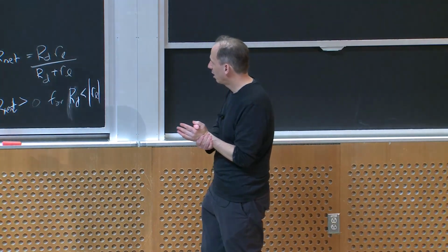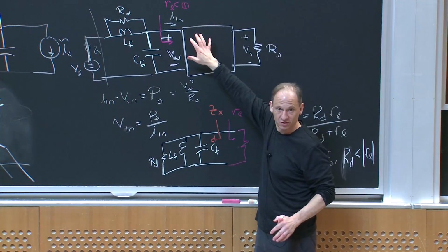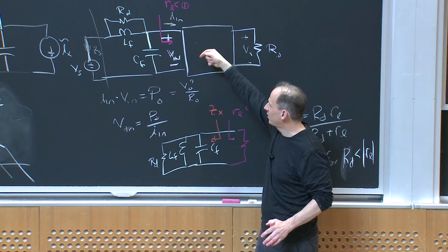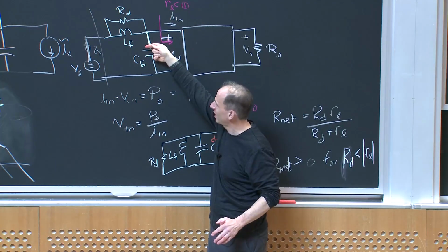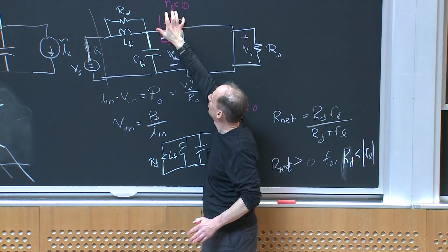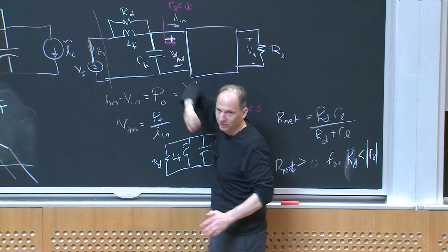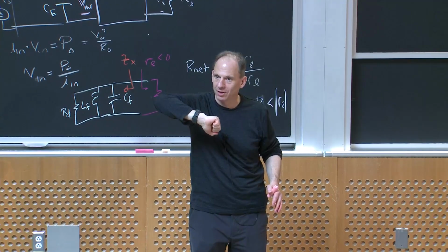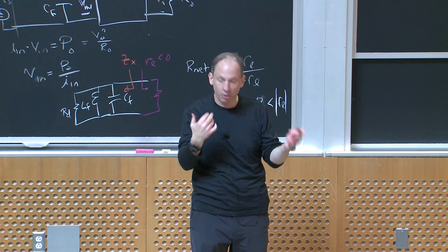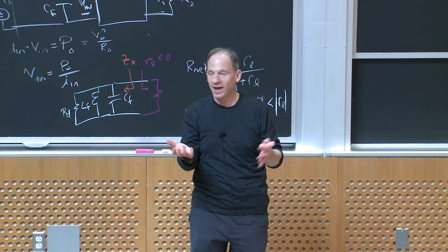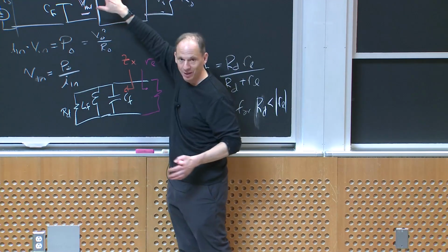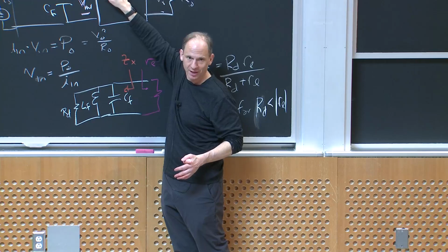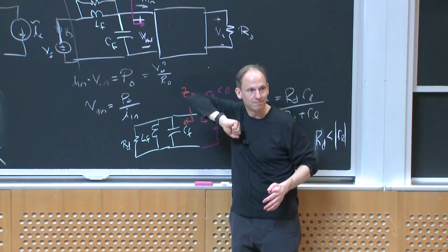First, if I assume my converter operates perfectly like this, we would like the maximum value of the output impedance of my filter, Zx, to be much less than the magnitude of the negative input resistance if I have perfect control. And that would be the case if I had a perfect converter that had infinite bandwidth in controlling the output anyway. So I need to meet that requirement.